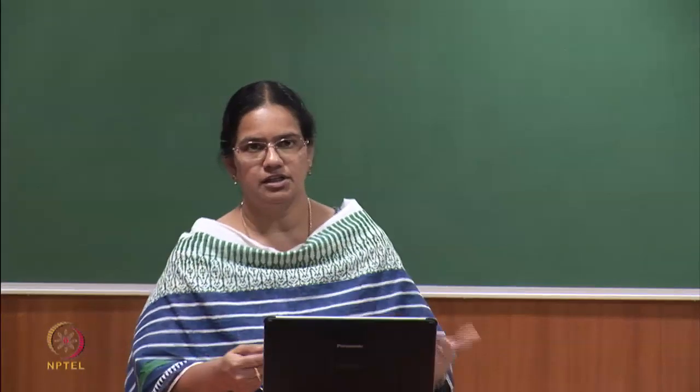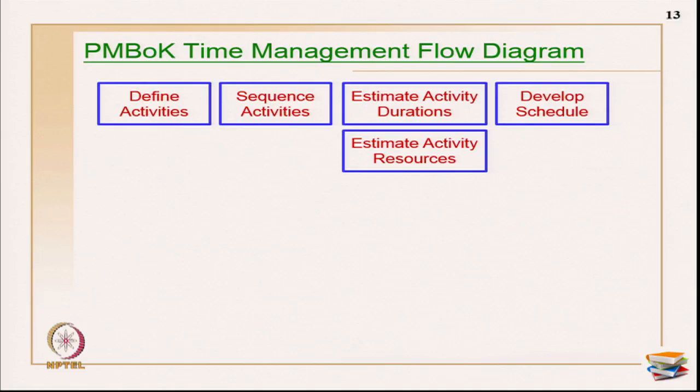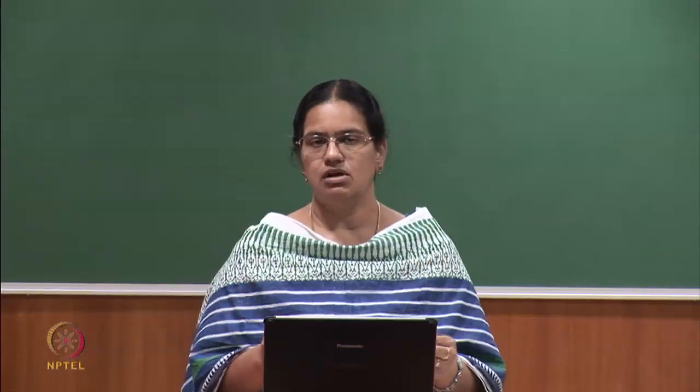In very simple layman language, project and activity both have similar terminologies, in the sense both have a definite start, a definite end, both have a specific objective, and in both cases they consume resources. Then why activities? Suppose you think about an auditorium project, it is very difficult for you to monitor a 6-month project in one go. So, these activities are nothing but the breakdown of the project into smaller groups, so that you are able to perceive the project, control it, imagine all the assumptions and then monitor the whole project. In that way we call them activities, and hence we have excavation, foundation, column footing, shuttering, de-shuttering, so many activities.